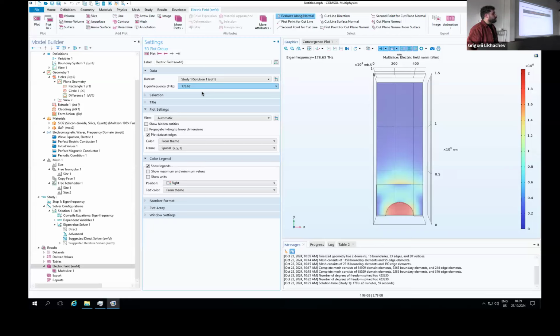You can simulate that whole thing, the mirror and hopefully even the taper, with numerical simulation. You can just create a simulation box around this, right? You put a port here and you inject the light this way. What's important is basically the phase of the reflected light.